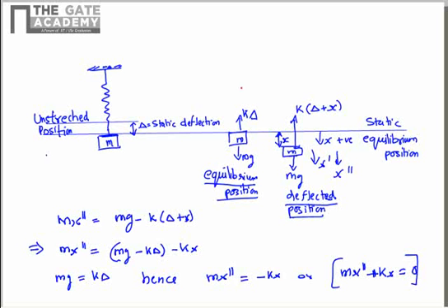So towards the end of the last video, we were talking about derivation of the equation of motion for free vibration. So in this case, there is no damping involved, or there is no forced vibration, no oscillating force function on the mass. And I've drawn the diagram neatly again here for our understanding that there is a stretch position, and due to the weight of the mass, the spring reaches an equilibrium position that is called the static equilibrium position. And now our problem is to consider the deflection above and below the static equilibrium position.